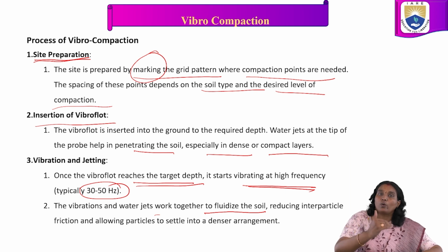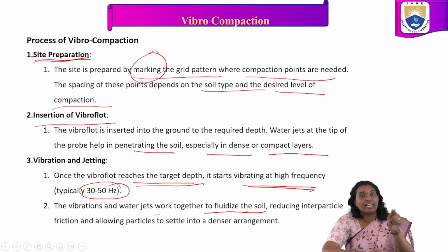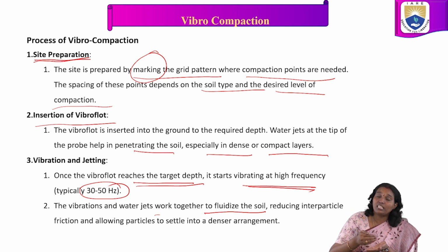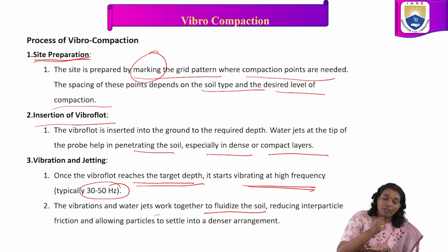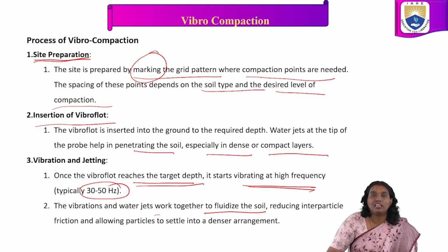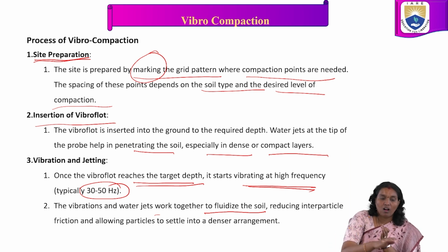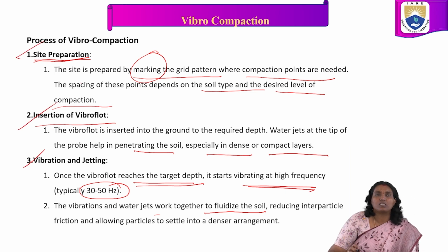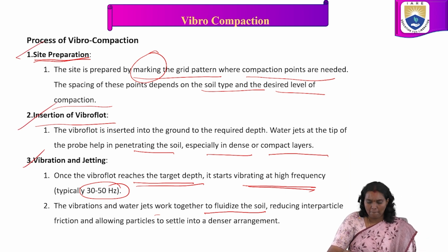So we process the vibro compaction very carefully, understanding how the vibration and water jets work together, how much the soil fluidizes, how much it flows and how much water it allows, reducing the friction and allowing particles to settle into a denser arrangement. These are all the processes we need to understand in vibro compaction.